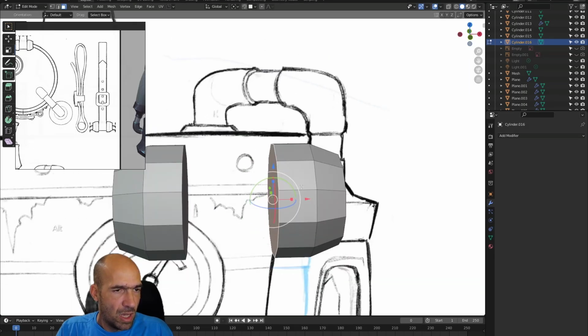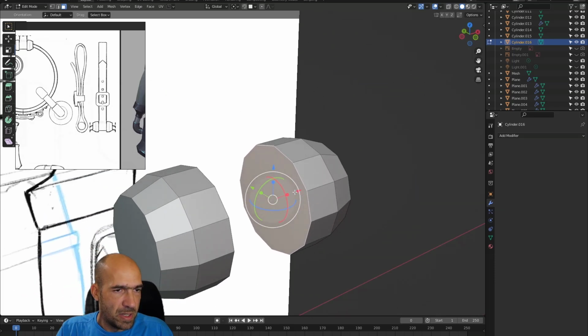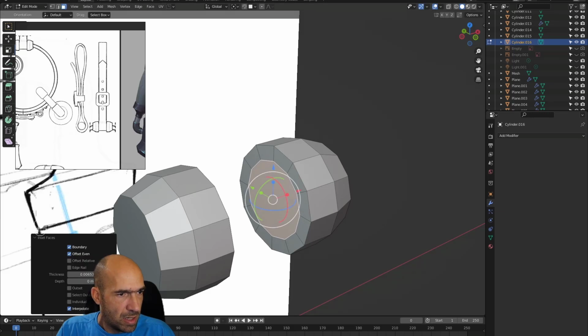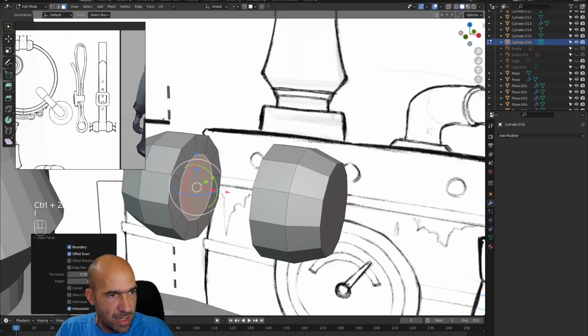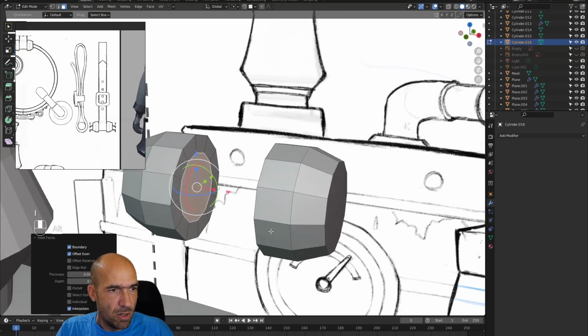And then in the middle, we can put something like, let me see, so inset here, and this will be 0.008, for example. I will inset this one by the same amount. It's very difficult sometimes to inset, by the way. So I will escape, Control Z, press again and press I. Now it works. 0.008. Enter. So it's the same amount.